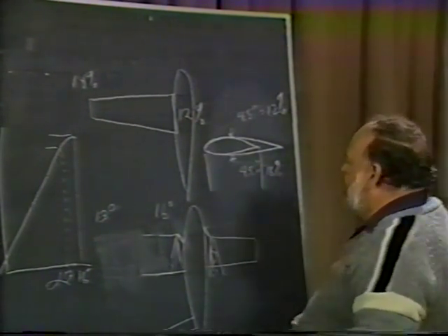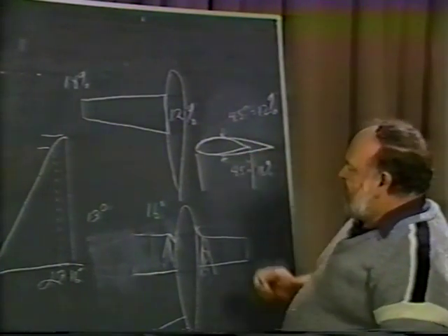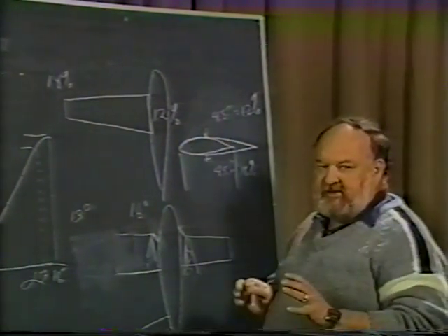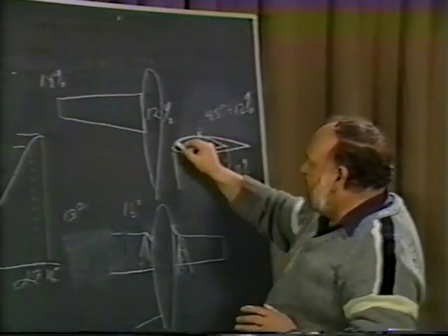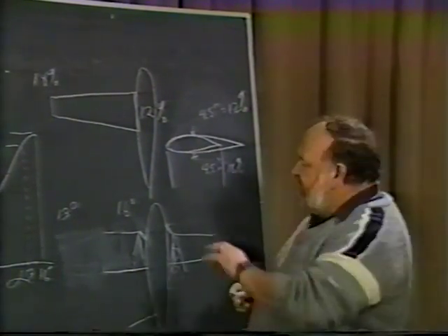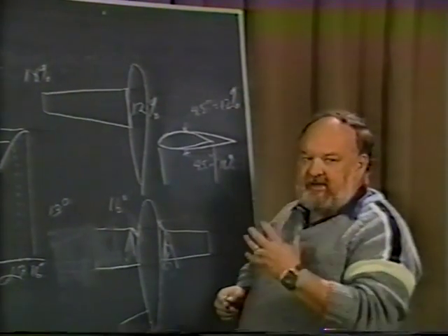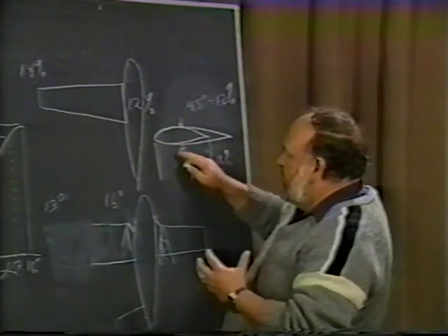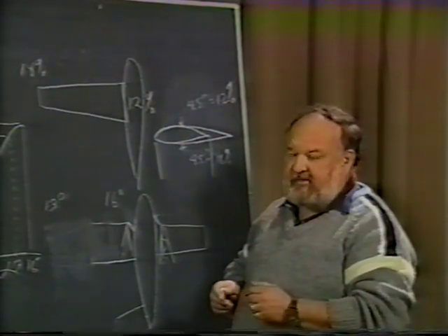Now what does this mean? Well, it meant that we ended up with an airfoil section outboard that had a leading edge radius in actual physical inches to be the same as it is at the root, but percentage-wise much, much bigger for the tip airfoil section. And therefore, when you have a thick airfoil section with a larger leading edge radius to it, it will give you a much higher angle of attack before reaching stall, and sometimes a much higher CL on it.